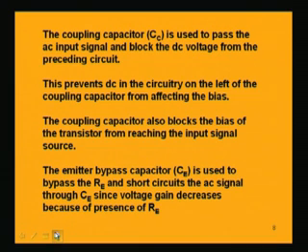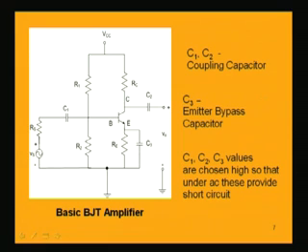Basically a transistor amplifier may have a number of stages in cascade, that is, in series we may have a number of amplifiers, so that the final amplified signal is large enough. So, instead of having only one BJT amplifier, we may have a number of BJT amplifiers in series. Now, suppose we have a number of stages coupled with this single stage, then the output at this stage, that means the amplified signal which we have here, will be fed as input to the next stage.